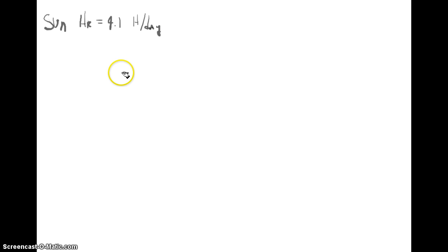since we know the sun doesn't shine every day, as engineers, we've got to make our best guess at how many days the sun is not going to shine. Well, in our shop in South Texas, we've looked at the data over 10 years. Our best guess for our conservative customers, if we choose 5 days of no sun, you can tell your customer that you will see less than one failure every 10 years. We don't expect this to happen but once every 10 years.